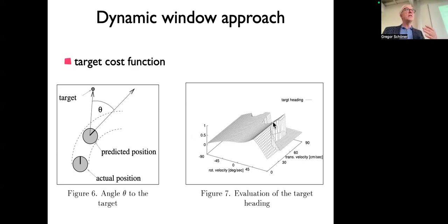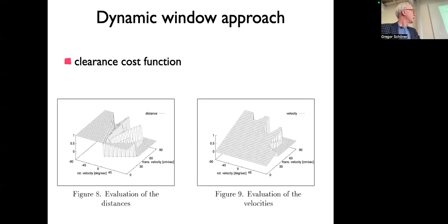This is a function that will change every moment in time when you're running, right? Because all these parameters change. And so there's a computation problem of making fast enough iterations so you can always get a good maximum. This is an example of the distance term. So large velocities are not so good, because then you might not be able to brake, and shorter distances are good. And then this pushes you to move fast. So if you only did obstacles, you would, of course, always go slow. And so you want to do something to force you to go fast. And then it's just heuristic.